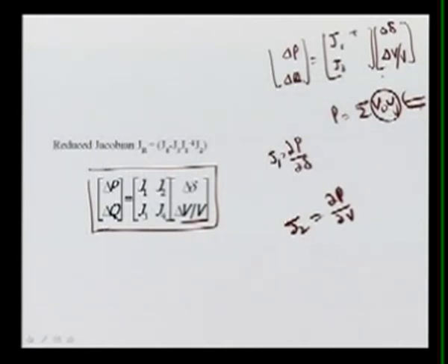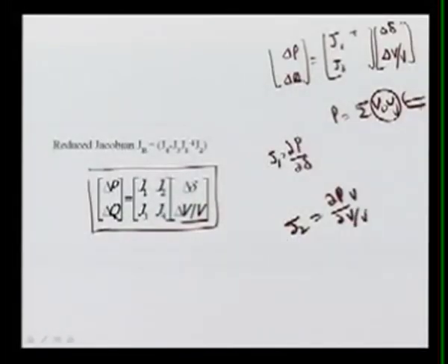As you know, the Newton-Raphson load flow method basically provides quadratic convergence. So we multiply here by V, and here we go for del V by V. This multiplication gives a complete quadratic and then we get faster convergence. So this is your Jacobian. If we are not changing the real power injection, this will be 0, and we want to see the relation between the change in reactive power and the change in voltage.